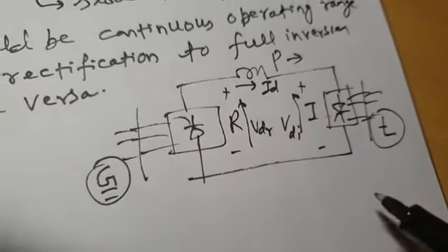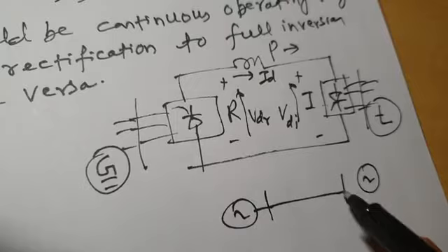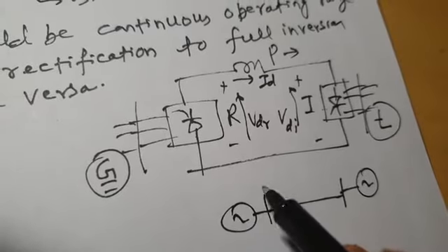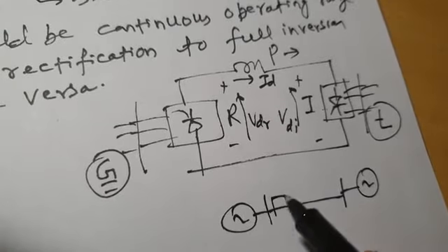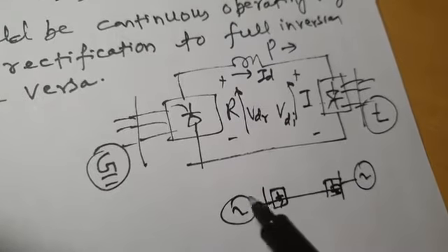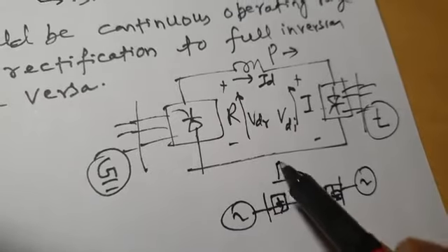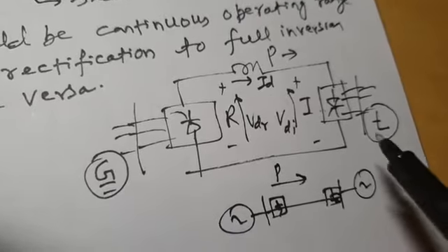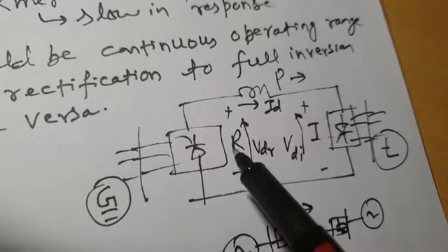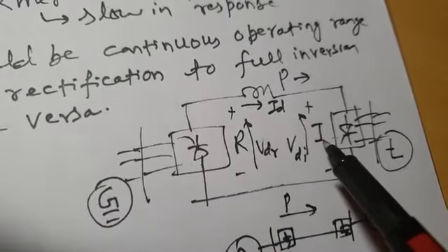But what this means is, you have a two-machine model. You have an AC side. You may have a rectifier here, a rectifying station, and you may have an inverting station here. This is the AC side. This is also the AC side. Power flows from this to this. Okay. So in that case, this converter operates in rectification mode, and this converter operates in inversion mode.